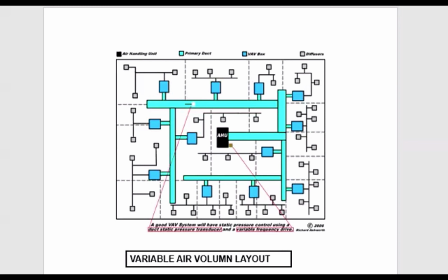All right, so looking at a floor plan, basically, we like to have our air handling units to be efficient, to come up through the center of the building, so that way it's an even dispersion through the pipe, through the ductwork, right, to each of the VAVs. And basically, as you see, when you start the run closest to the AHU, that likely will have the smallest opening to get air through because it's at its coolest.